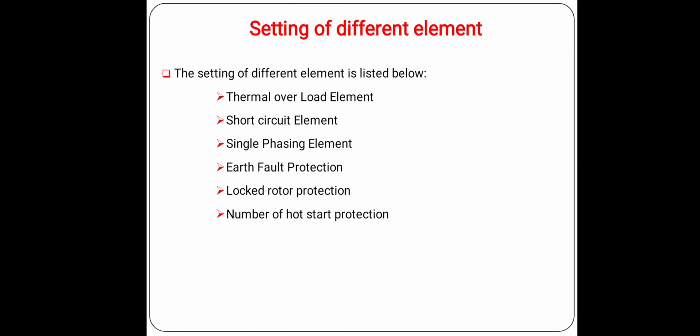Number of hot start protection. Here we provide the number of starts allowed in a specified time duration. By this we limit the number of hot starts given to the motor.